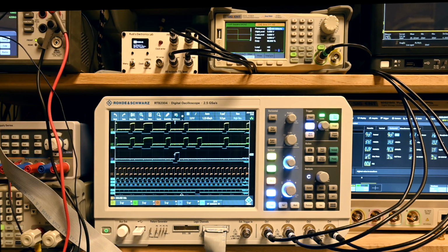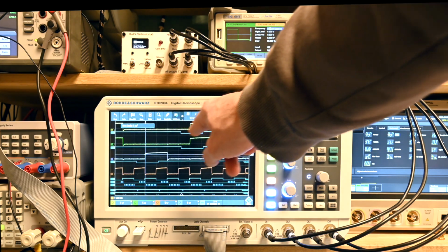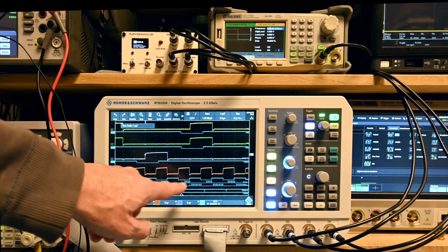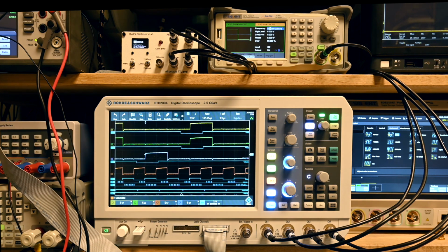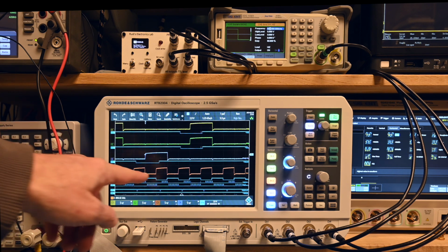Do you see these little spikes here? So what we see is basically the wait loops. Let me make it a little bit bigger so we can investigate them a little bit. Again, we see the timing problems a little bit more. And so here we can see the wait loops. And it is these wait loops that take care that every time the Arduino is waiting a little bit for the right moment to bring its values into the flip-flops, then the flip-flops are clocked out exactly via the steady clock. And then again, the Arduino has to wait for a moment until it can properly deliver its data. And it is the proper right moment.